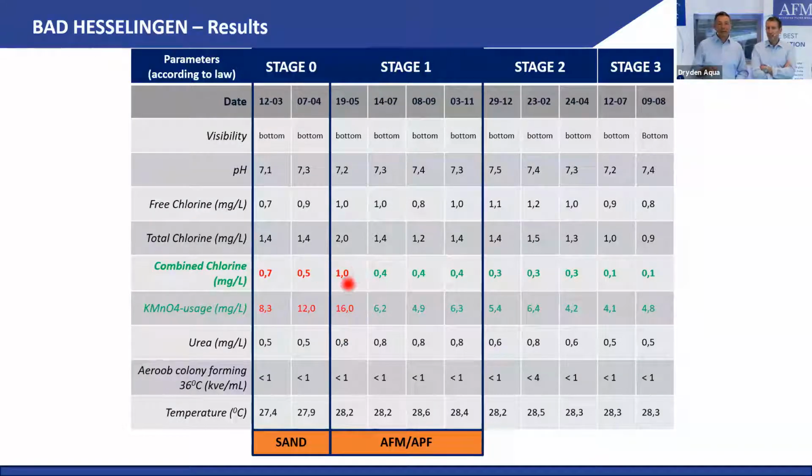And here you see some red numbers, higher than we were before. And maybe sorry to tell this, this was not funny. Pomats got their first result, the red ones here, and they were in panic, and they called me and said, Dominic, we have a huge problem in this pool, jump in a plane and come. And I love to go to the Netherlands, but maybe not within 50 minutes. So I asked, are you sure you're backwashing correctly? Yes, we do. There are 2 pumps to backwash the filters. I said, do me a favor. It's not that far away from you. Go and make a video of the side glass. I want to see the backwash process.